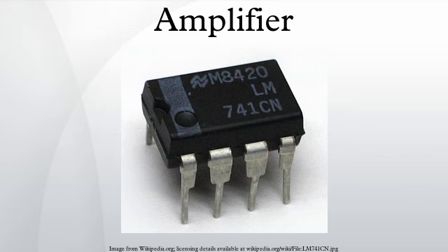Frequency range. Depending on the frequency range and other properties, amplifiers are designed according to different principles. Frequency ranges down to DC are only used when this property is needed. DC amplification leads to specific complications that are avoided if possible. DC blocking capacitors are added to remove DC and subsonic frequencies from audio amplifiers. Depending on the frequency range specified, different design principles must be used.